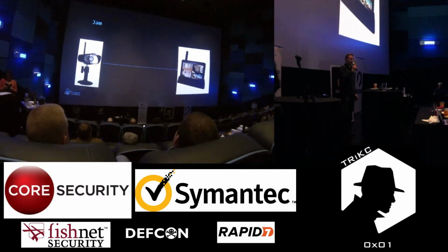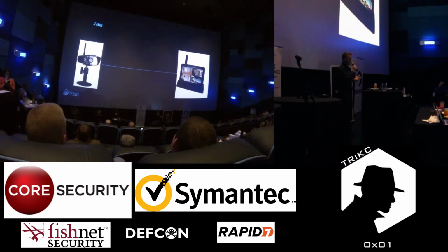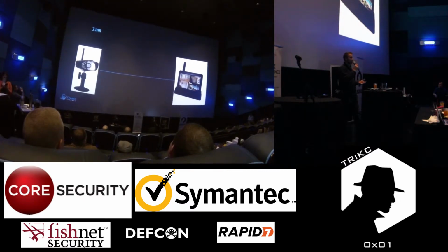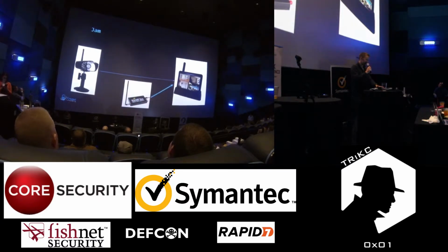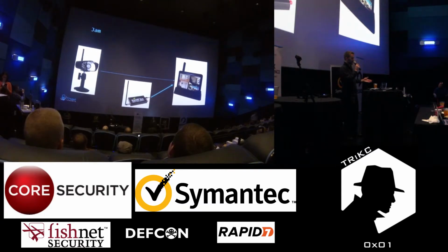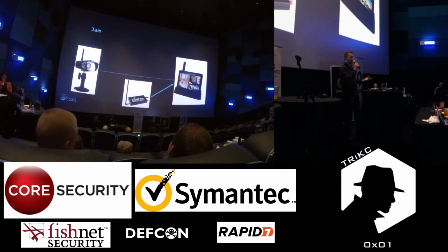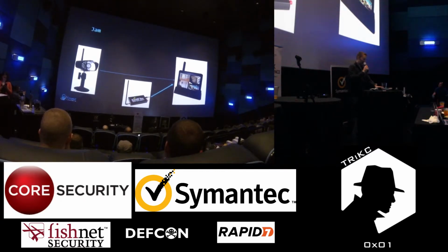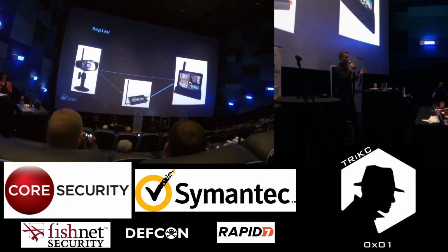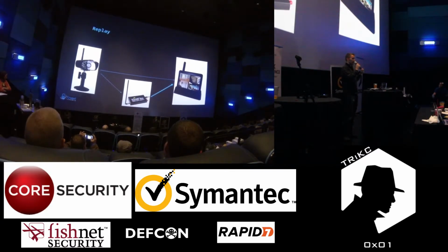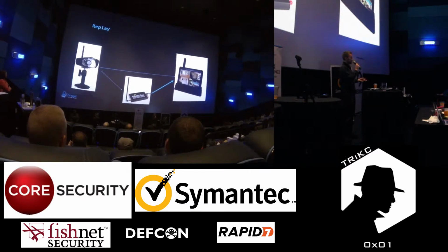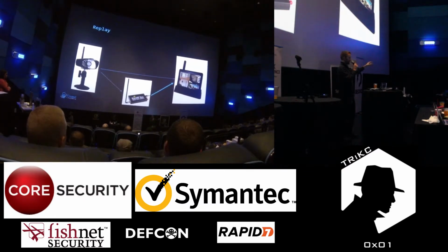So if you're looking at a radio broadcast frequency like a home surveillance system, one option for an attacker is to jam that system. So if you have a HackRF like I have here, and let's say that's at 2.4 gigahertz, you can actually broadcast a stronger signal and override that frequency so nobody sees anything. Another option is to replay that signal. So if you record a kind of a blank signal or something where nothing is happening on the security system, you can actually just record that info and then broadcast it back.